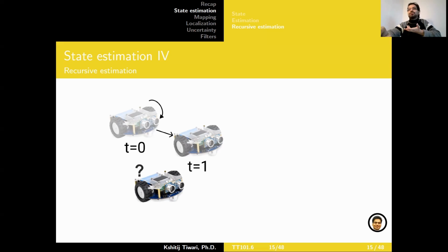But the robot doesn't know this, because as far as it is concerned, you give it one full rotation, the robot thinks it does one full rotation because that's what the sensors report. And then there is some ambiguity in where it is. But if you have a landmark, for instance, like a star, you can use how the environment is perceived. Given the action, the environment would have looked slightly different, but now it looks different because of this offset in where you should be and where you are. You could use this landmark to correct for these errors.